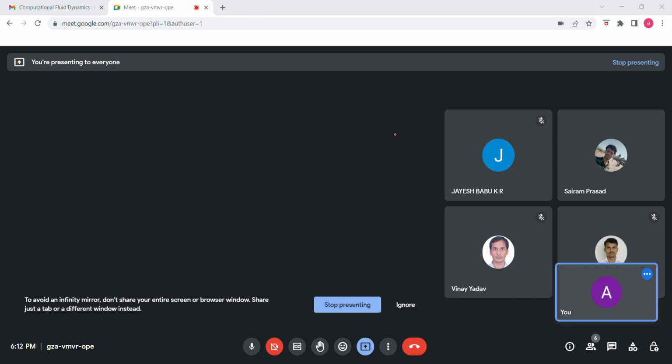Heat flux at both ends is given. If heat fluxes at both ends are given, we cannot solve the problem because both will be derivatives, and so we may not be able to get the proper values at all the points. So this condition is not applicable, whereas the first one we can do. Next, heat flux and temperature at one end is given. If both values are given at one end, we do not know how the temperature is moving in this direction. So this option is not applicable to solve the system properly.